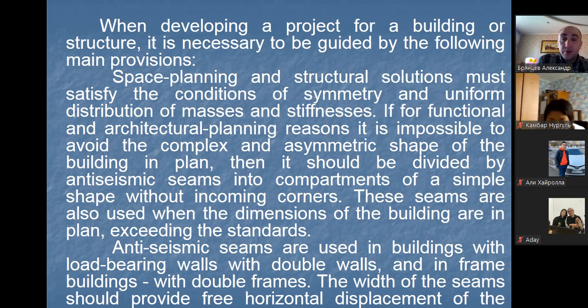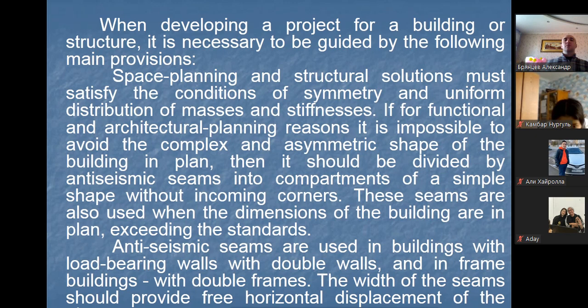So, during development of the project, it's required to follow the main provisions: space planning and structural solutions that satisfy conditions of symmetry. On the next slides, we'll see what symmetry means, the uniform distribution of mass and stiffnesses, and how important it is to use symmetrical construction as a way of protection from seismic destruction.